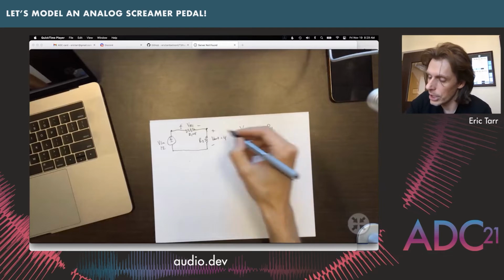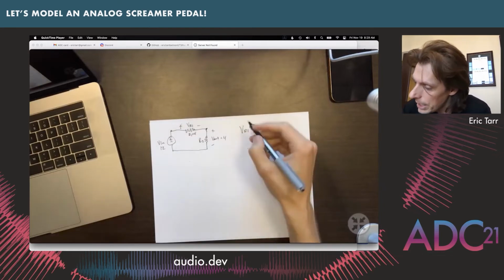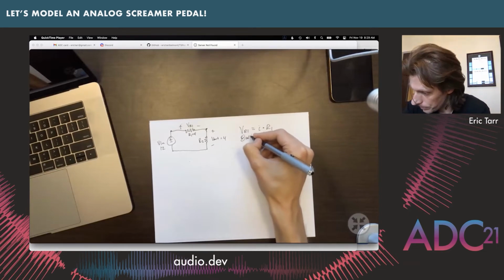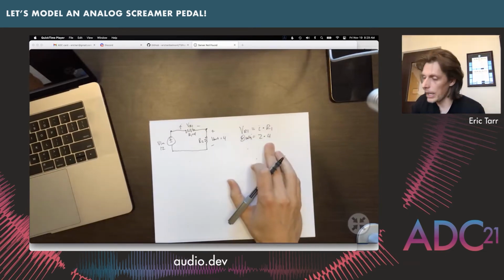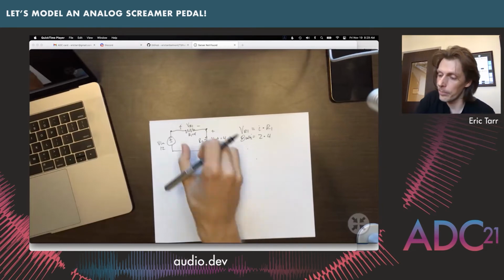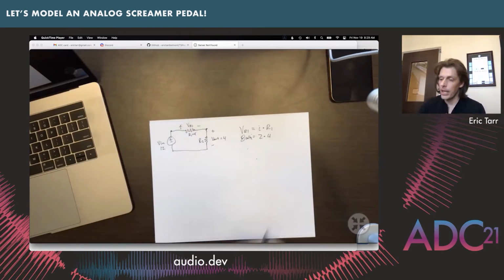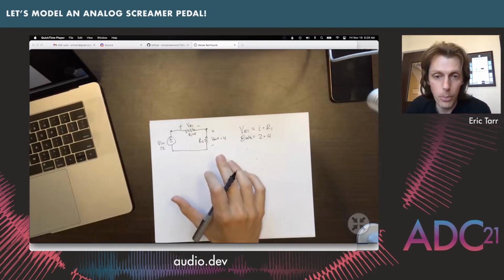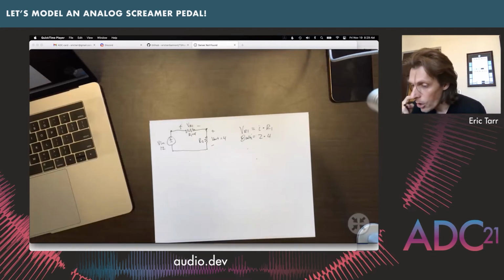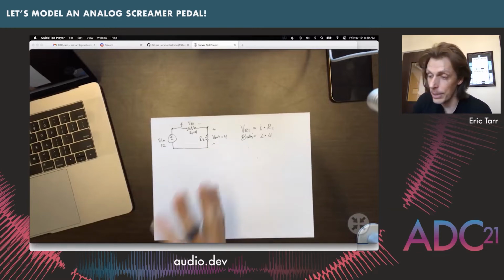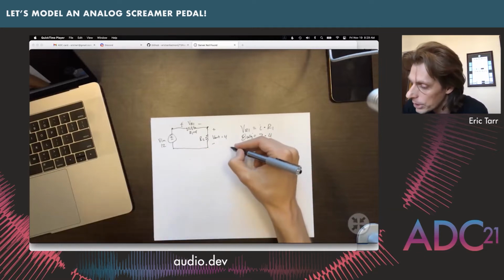So the voltage across this one right here is going to be 8 volts. Okay, so that's another value in our circuit that we could calculate. This also brings up a very important point about working with circuits like this: this one right here has a special name that we'll want to know about, called a voltage divider.